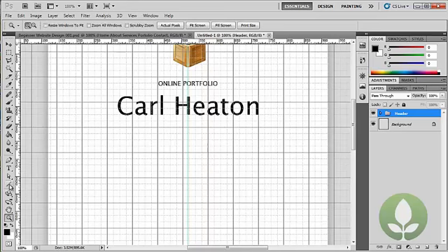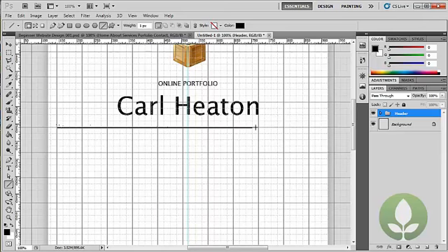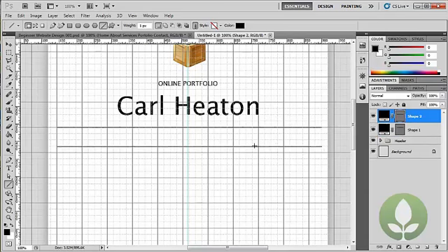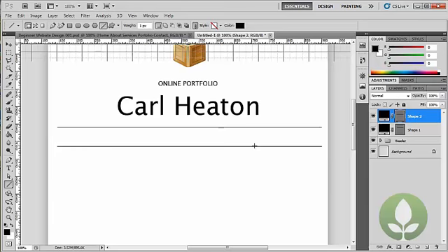We've got that selected now, so I'm just going to click on there, make sure I've got my line tool selected. It's at 1 pixel and it's black. Now I'm going to leave 2 spaces here, 2 of these boxes, and I'm just going to go from the side, leaving around about 1 space there, and I'll click and drag, pull over. Because I've got the grid there, it makes life a lot easier, and then let go. Alright, and if I just do that again, I'm going to give three of these squares down. I'm going to click and drag and move over and then let go. Now if I press Ctrl and H, there we go, there's my navigation.